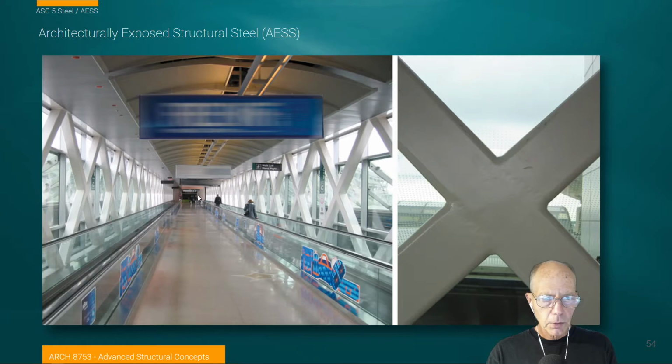So here we have two, we have this idea of these structural crosses, very much about a design aesthetic. The architect probably wanted these crossing instead of just being diagonal truss-like elements. And in that case, these two intersecting pieces of steel had to be joined to each other. These aren't available off the shelf as X's. They're not fabricated. They're just tubular steel. And so if you look above my head here on the right-hand side, you can see this hinting of where that weld, that joinery. So this is the full solid piece going from top to bottom here. And then these transverse elements here are welded in.